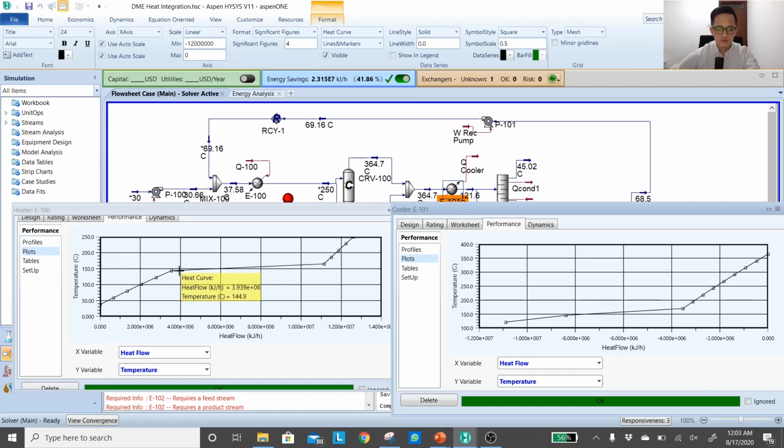And then in the center section of the heat exchanger, this is where vaporization happens. That's why the gradient decreases, and that will require extra attention during the sizing of the heat exchanger. And after it becomes saturated vapor, we continue to increase the temperature, so the third part is the sensible heat in terms of the vapor phase.